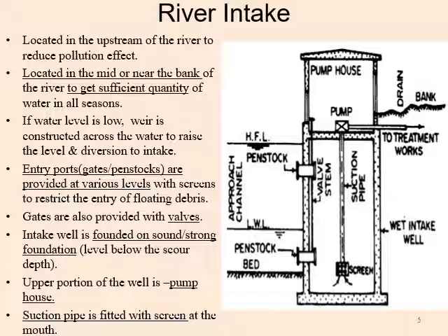The intake well is founded, means it is constructed, on a sound or strong foundation, below the scour depth. Scouring can happen at the river bed level, so the intake well should be constructed with concrete over a strong foundation.